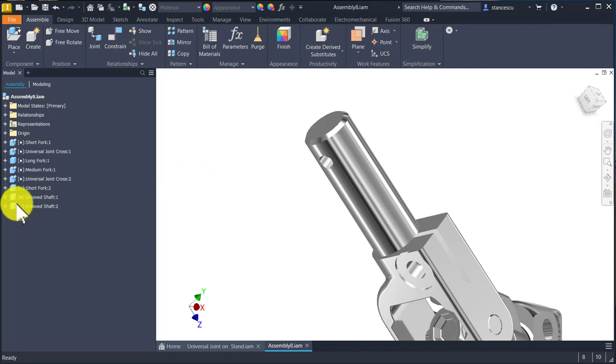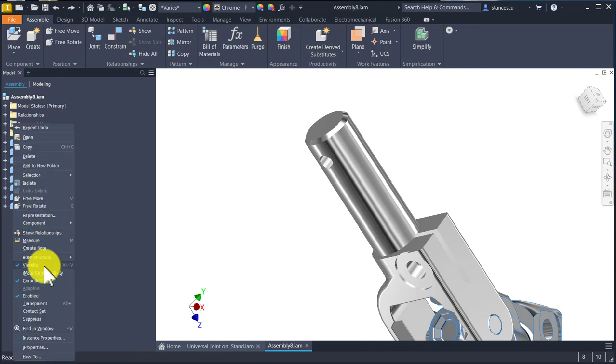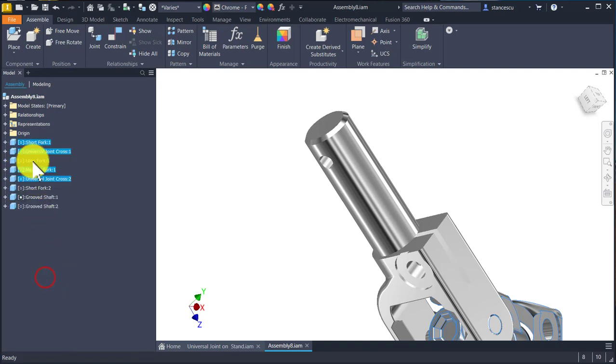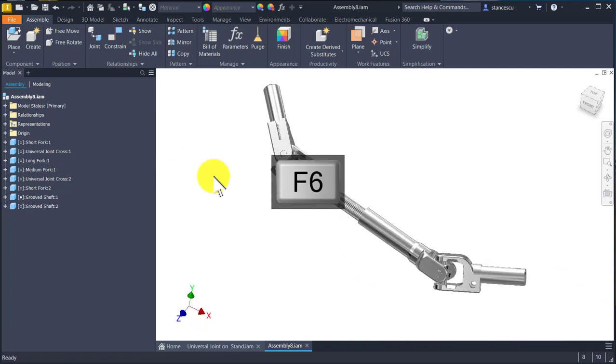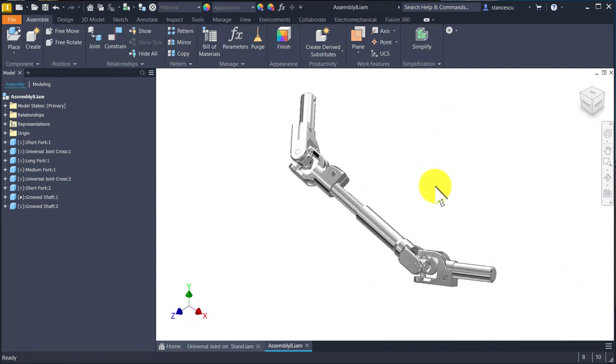now you see some of them are not grounded, the others are grounded. I apply not grounded for the components which appear to be grounded, having that pin, as you can see. Now there is no pin here, and we have that free to be moved.